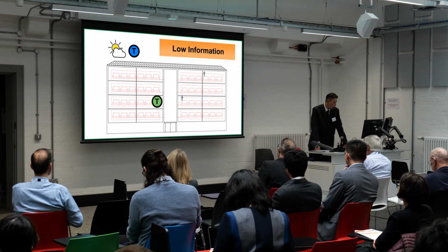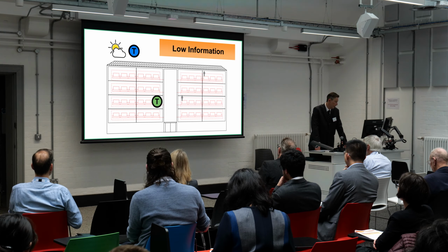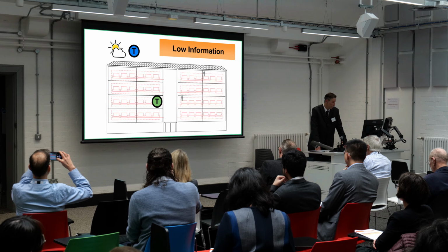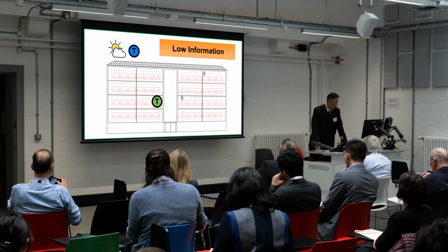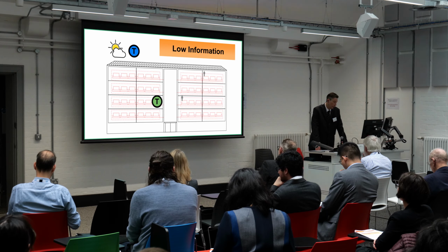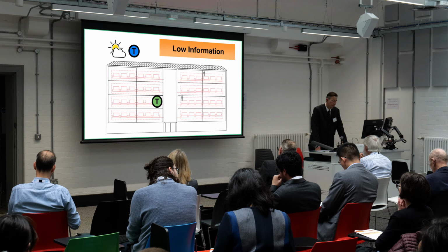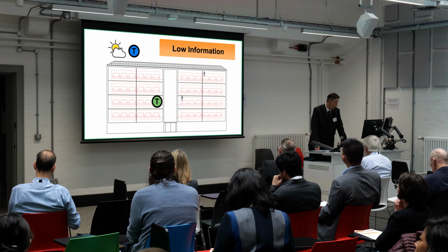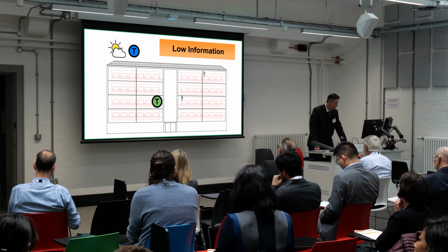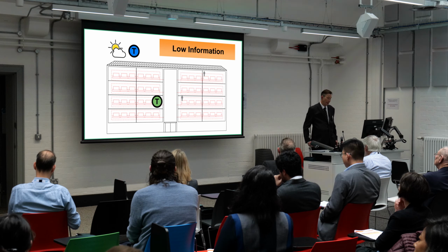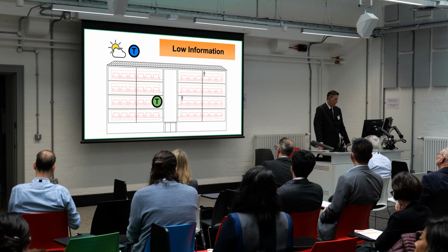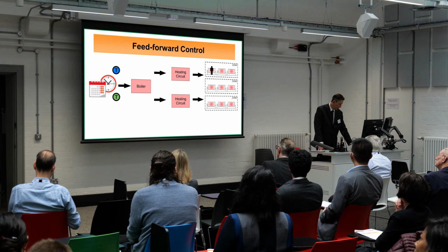So in this example, we've got an outside air temperature sensor, which gives us an estimate of the steady state losses of the building, and therefore how much energy we need to put in to make up for those losses. And 1 or more inside air temperature sensors, which gives us an idea of the dynamic conditions. How much is the building cooled down? How much do we need to heat it? When do we need to switch the heating on? But of course, where we put that sensor, or those few sensors, is a big question, because where does one place one to be representative?